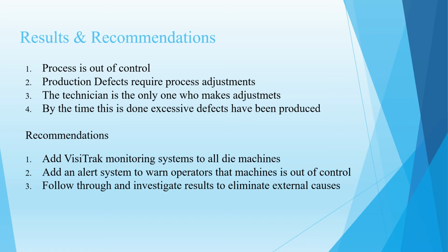This will provide the ability to use a real-time alert system to warn the operator that the process may be shifting beyond the control limits. The machines' andon lights will alert the technician that their attention is required at that particular machine. This will lead to a reduction of defects in parts, which reduces rework.